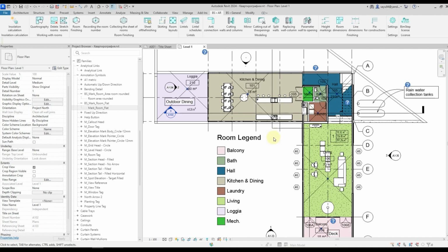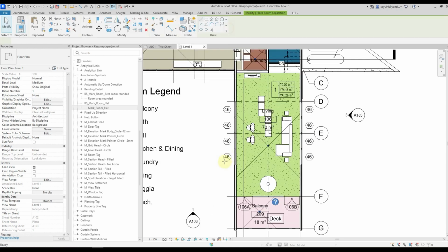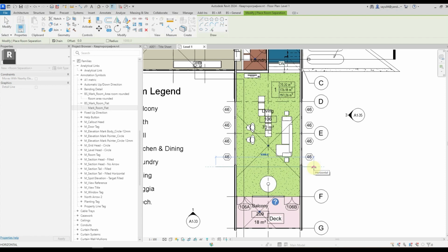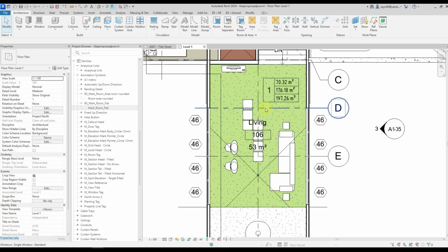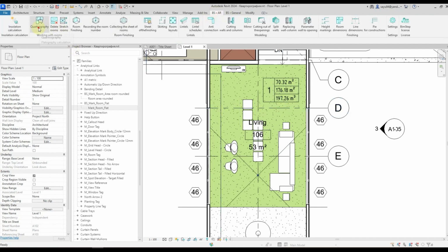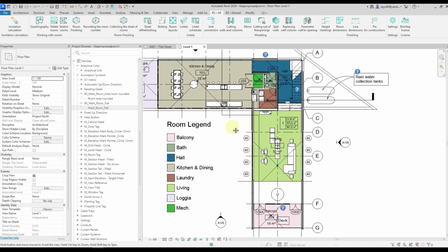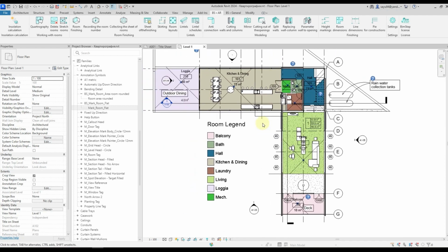That being said, if you have something changed in the area characteristics, restarting the plugin will fix it. Let's divide the residential premise, thereby reducing the area from 70 to 53. Next, if you run the apartment calculation plugin again, done, the values will be automatically recalculated. Now, for this flat, we don't have 70 square meters of living space, but 53. In the same way, all the other values are decreased. So with the help of restarting the plugin, you can immediately receive up-to-date figures within your flat.